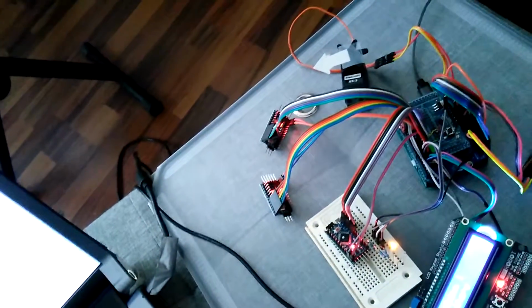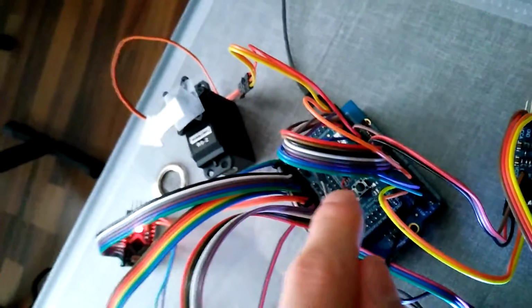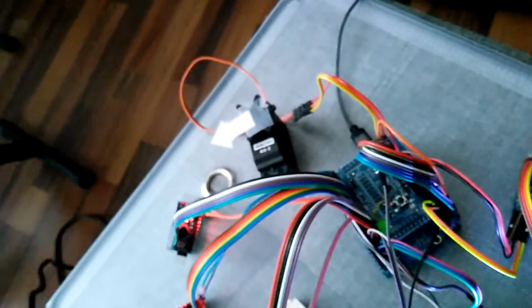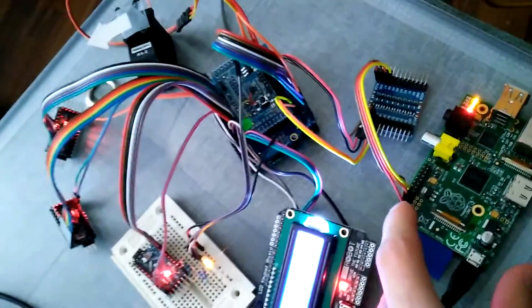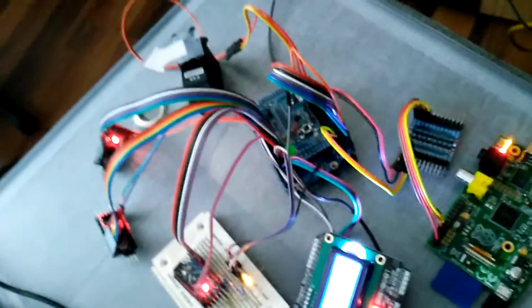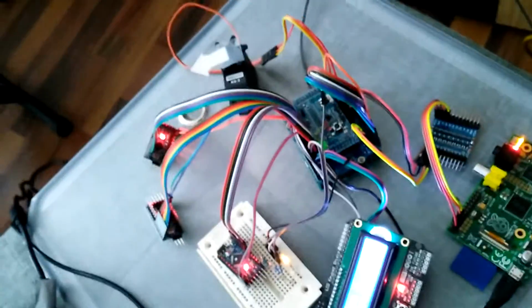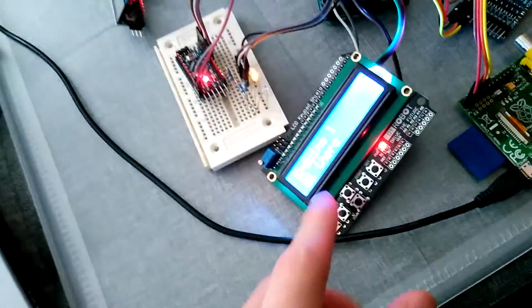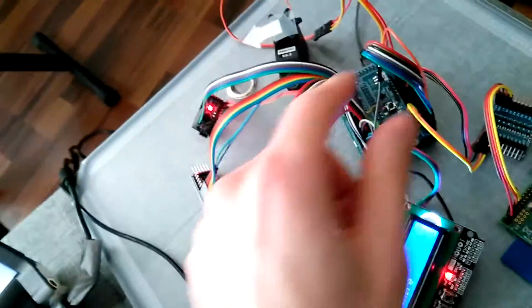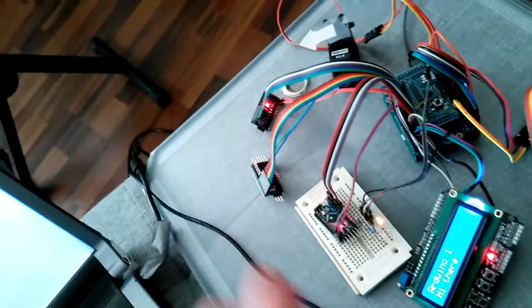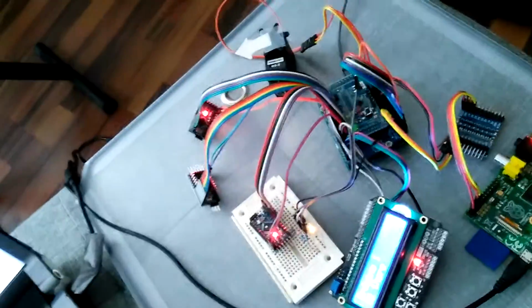The Arduino Leonardo UART is also connected to the iolinker board, which I use to allow the Raspberry Pi to send messages to the Arduino Leonardo. In the example application, every Arduino tries to write out a message to the LCD, but the iolinker board only wires up one Arduino to the LCD at any given time, so only one Arduino gets to control it.